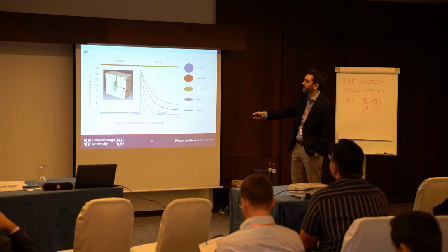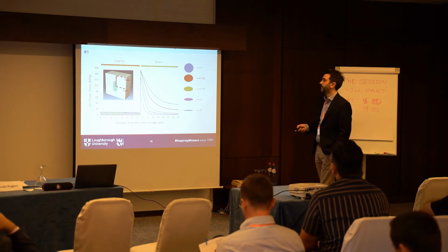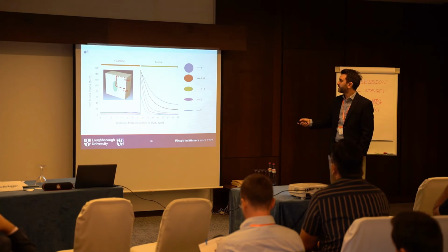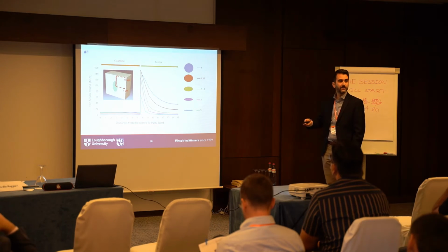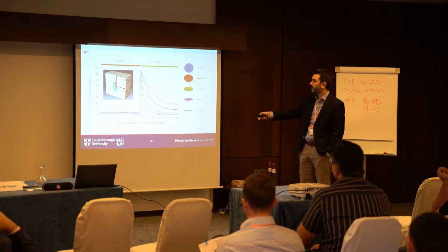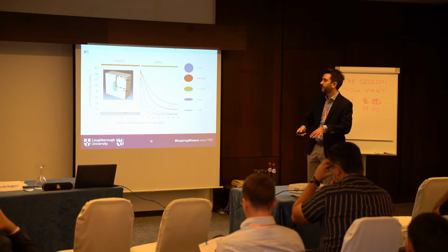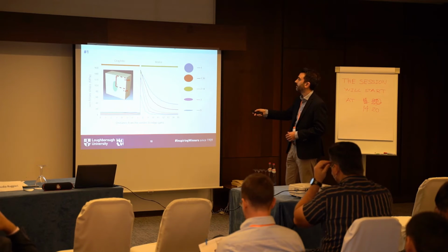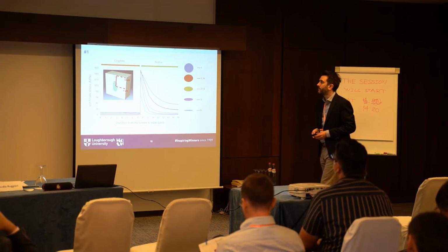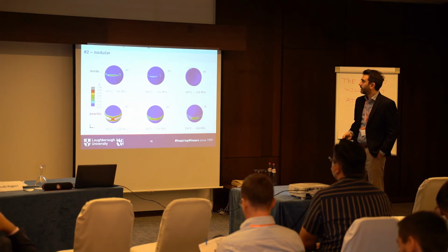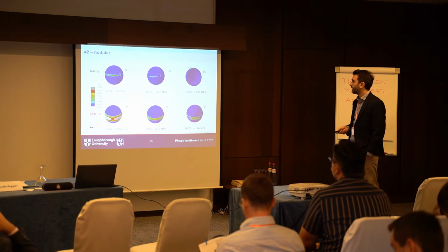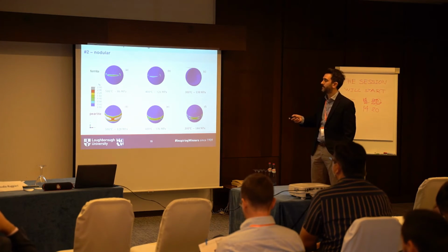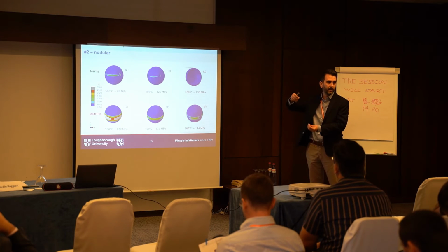stresses, the plastic stresses across this line. This is a bit contradictory because you again expect your more elongated one to have higher stresses, but because damage has kicked in now, the load bearing capacity of this material has dropped. So that's why you see the more elongated one down there, and then up here they all collapse practically to the same point.